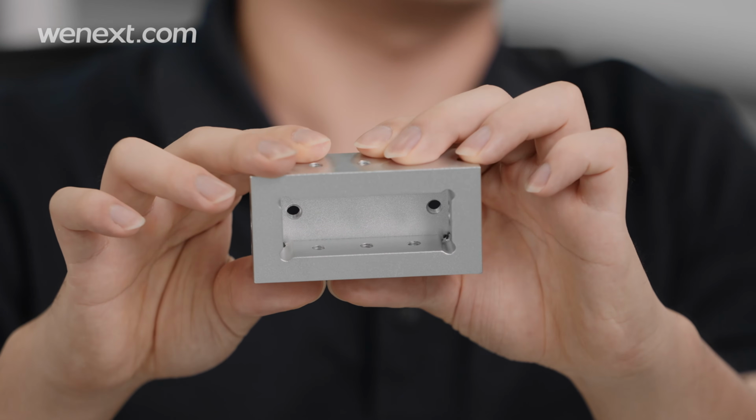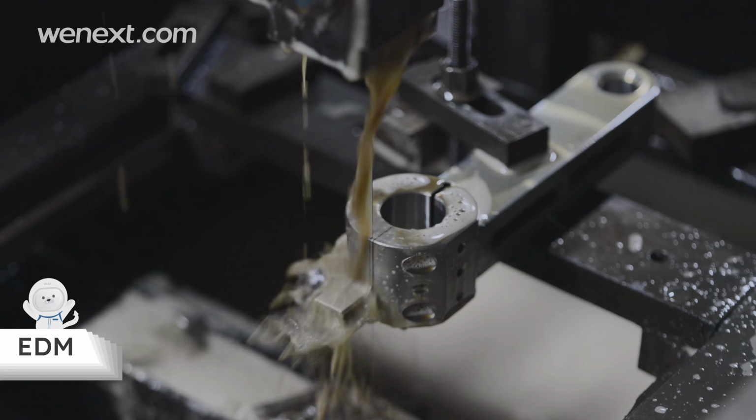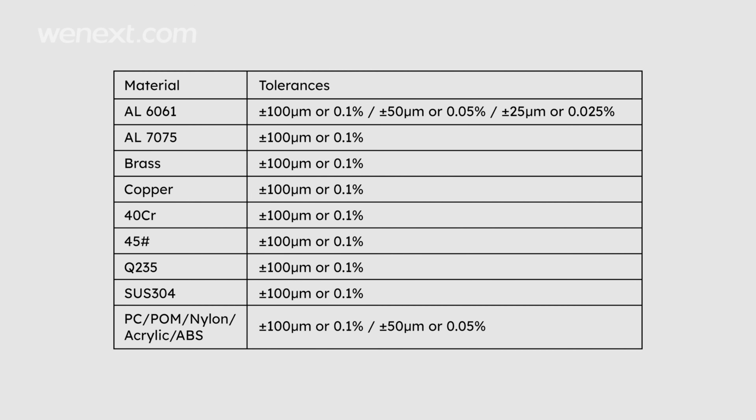CNC also has limitations. It cannot cut an inside right angle. Even if the blade is sharp, it is impossible to cut a right angle of 90 degrees inside the product. But if you have specific requirements, EDM wire cutting can do this for you, while the cost will increase significantly as well. CNC generally produces parts with high dimensional accuracy. However, if you have tighter tolerance requirements, it means the chance of part failure will increase, and so does the cost.